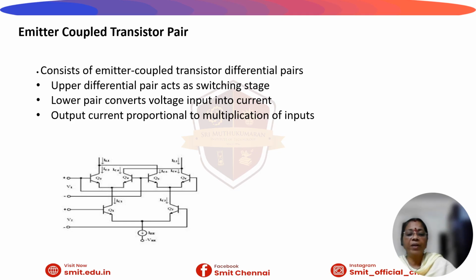Four-quadrant operation is achieved, as the Gilbert cell allows both input voltages V1 and V2 to swing between positive and negative directions. It operates in the current domain, leveraging the logarithmic exponential relationship between the BJT base emitter voltage VBE and collector current IC. This makes the cell highly temperature stable and inherently linear. Its differential topology cancels out many unwanted mixing products and distortions, resulting in a significantly cleaner output signal.